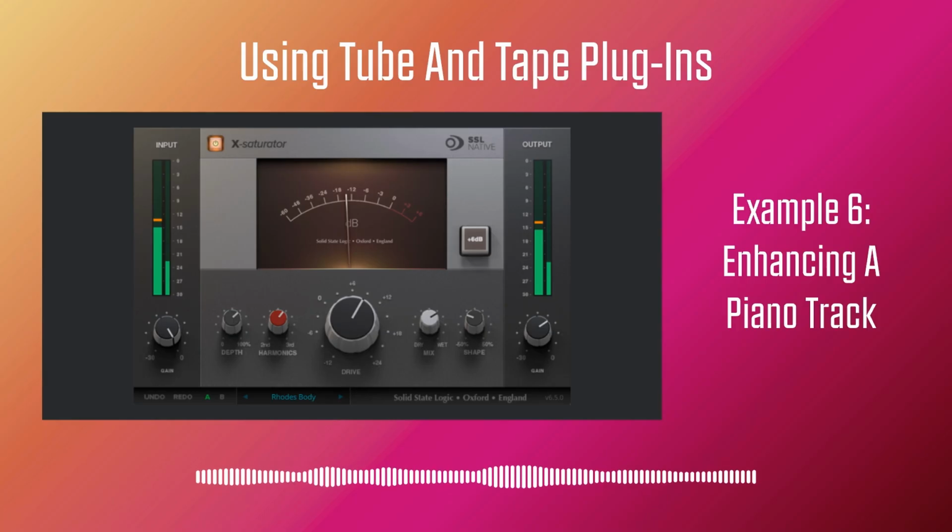I've set the blend value to around 60%, as I want to generate both second and third order harmonics, but leaning more towards third order harmonics. Depth, which controls the distortion amplitude, and the wet and dry mix are both at around 65%. I've used the shape function and steered the distortion edge towards a smoother response, as I don't want to give a hard edge to the generated harmonics.